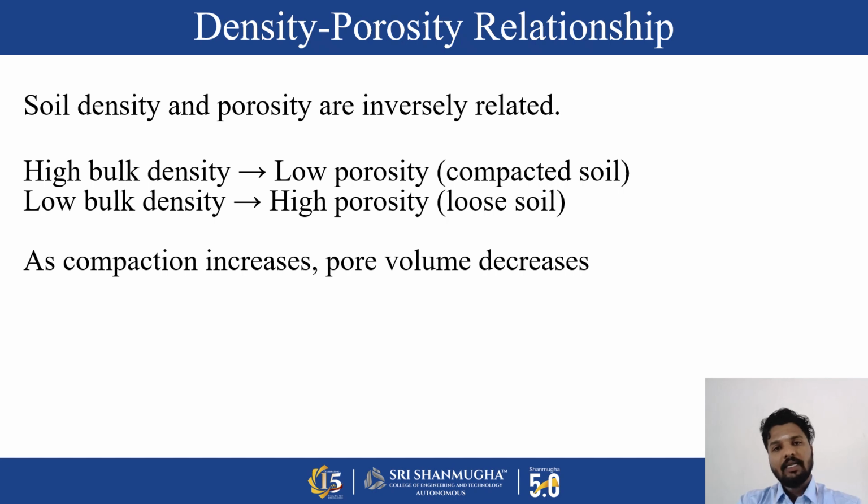If there is high bulk density, it means there is low porosity in the soil. That gives the characteristic of compacted soil. In loose soil, if there is low bulk density, it means there is high porosity. So as compaction increases, the pore volume decreases in that soil.